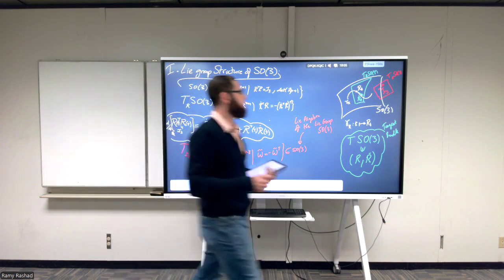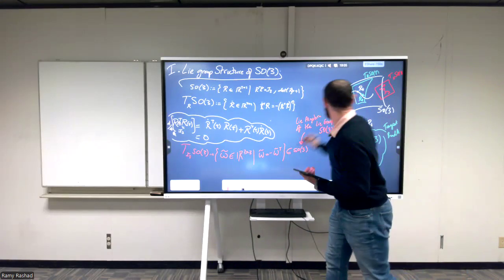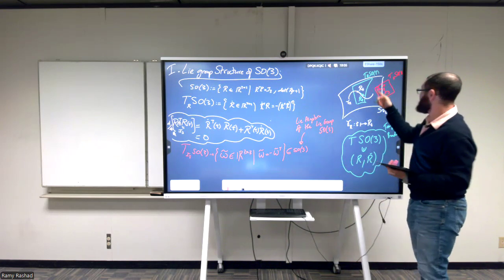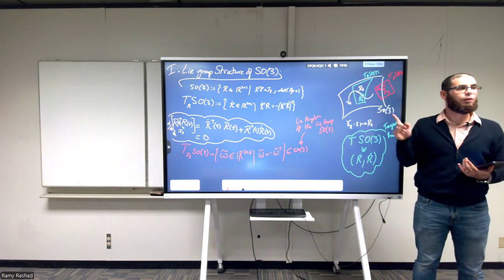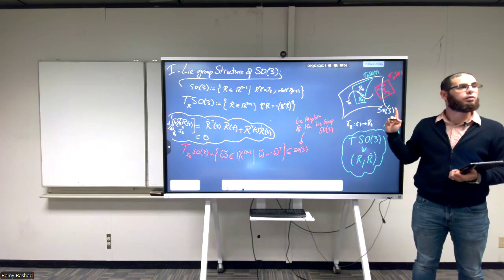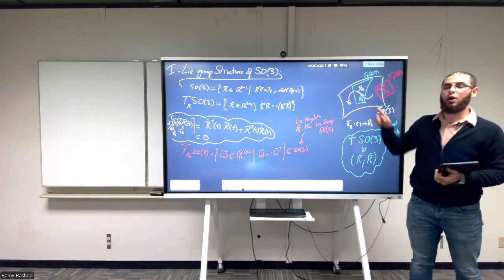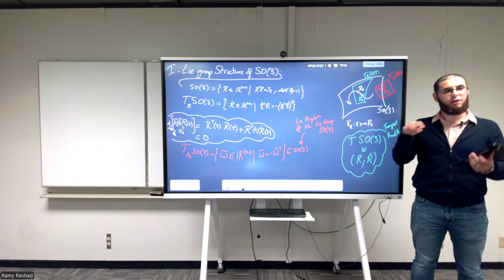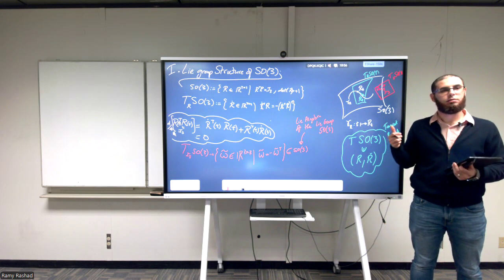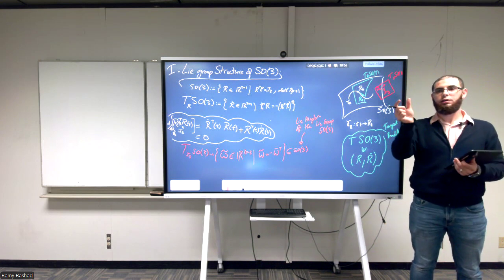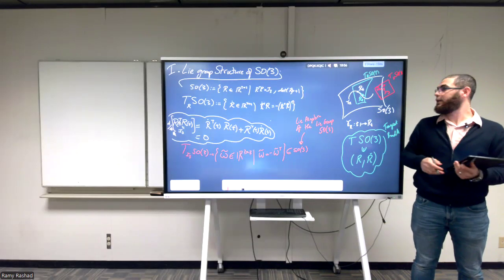So now the question is as follows. So omega hat is a vector here, and r dot is a vector here. Is there a relation between both? Can we map tangent spaces to one another? Or in other words, can we map even this R to another R here? If I give you 2 R's, can you make another R between them? Does the group have this operation? Yeah, the group operation. The group operation takes 2 R's and gives you a third one. You can always do that.